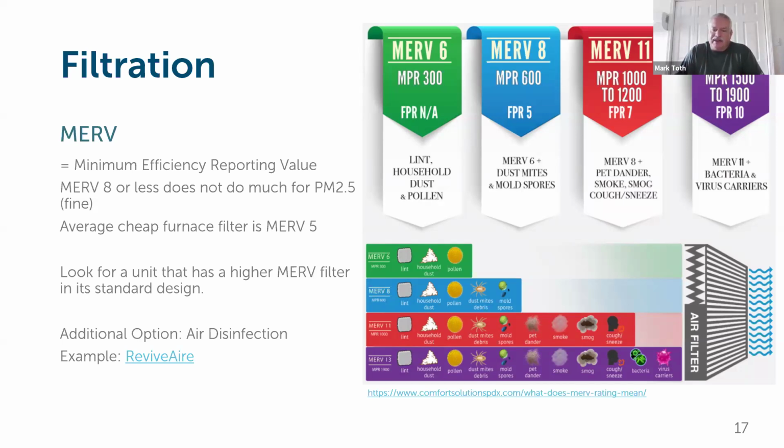But once again, in an ERV, HRV application, that type of filter is not going to be as important as it is in a system that's recirculating air in the house, because we have to remember, we're bringing in fresh air from outside. We're hopefully not going to have viruses and bacteria. Hopefully our intakes are going to be in a clean spot and we're getting clean outdoor air.